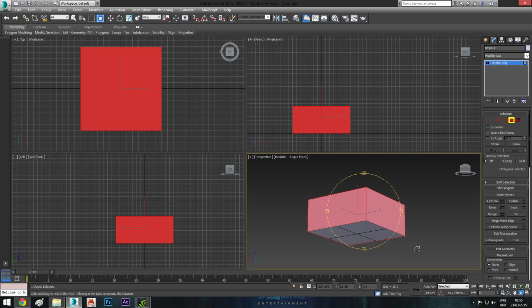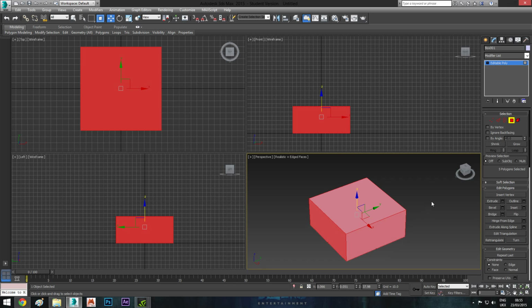So next thing is, how do we actually add detail to this piece of geometry? What we have is an edit polygon panel here, which does all sorts of things. For the moment we want to do insert, which will insert another polygon inside this polygon. So we'll click settings. Avoid clicking this button and just click the settings button. Now we have a wee panel here.